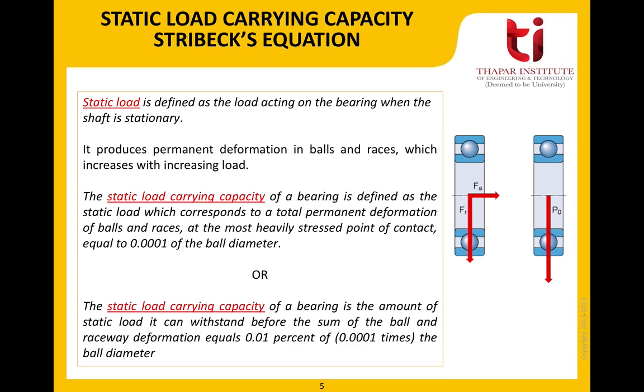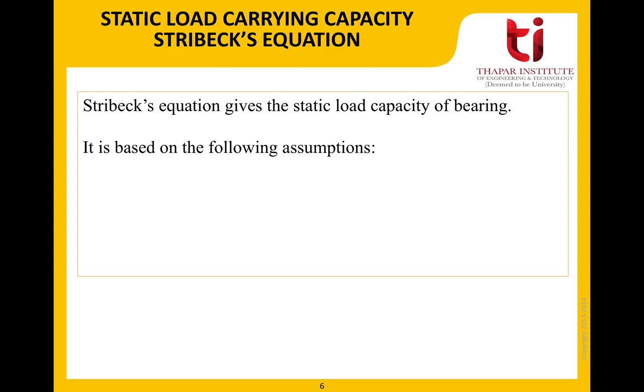Another thing that you need to remember is that the formulas to calculate the static load carrying capacity are given in standard data books for different types of bearings. However, while selecting bearings, it is not necessary to use these formulas. The reason being, whenever you go to a market to buy bearings, the value corresponding to the static load carrying capacity is already provided by the manufacturer in the manufacturer's catalog. But we need to understand how these formulas are derived. So we'll talk about the derivation now.